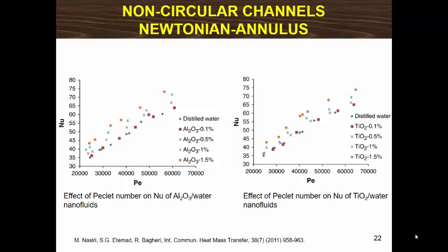Comparison with previous studies on the heat transfer enhancement of nanofluids in circular tubes shows that the enhancement of Nusselt number is lower for concentric annular channel. As mentioned before, the enhancement of Nusselt number reveals that the heat transfer performance of nanofluid is under the influence of various parameters, and thermal conductivity is not the only main factor. Nanoparticle migration, Brownian motion of nanoparticles, decrease in thermal boundary layer thickness, and possible slip condition on the wall are other possible reasons for enhancement of heat transfer coefficient.